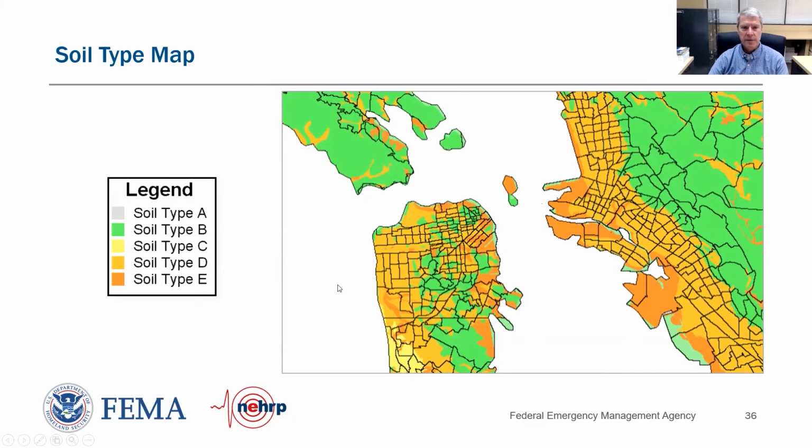Regional maps. So here's a figure of the Bay Area showing municipalities outlined, and then they're color coded based on the soil type. So it's pretty easy to look at this map where your building is at, and then to pull out the relative soil type, whether it's an A, B, C, D, or E, and then utilize that information for determining soil type and whether or not we need to modify the basic score for a better soil or a soil that's not quite as good, type E.